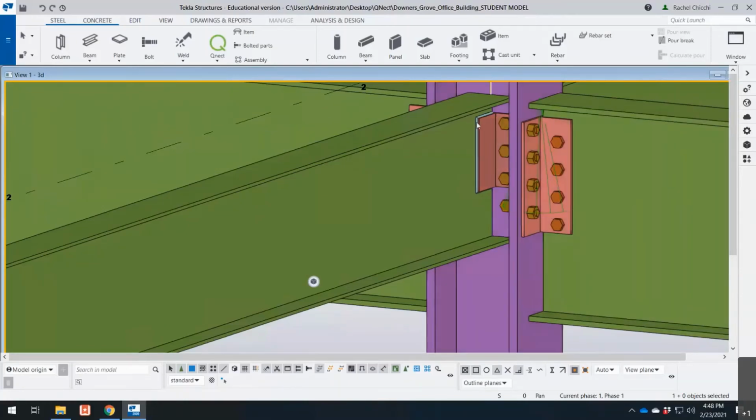So here we have an angle up higher and it's using the top 3 bolts. On the other side of the connection, it'd be using the second, third, and fourth bolts. What this does, it allows for that issue of erection. So we can still connect both, and you could use in this example the top set of bolts on either side as your 2 erection bolts. On the other side, you can use the lower ones that wouldn't conflict with this connection, and then you don't need to have any kind of erection seat.